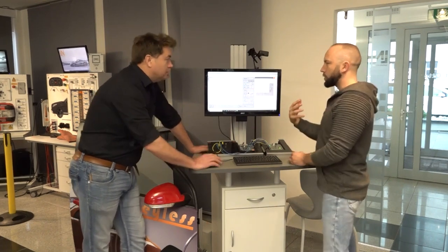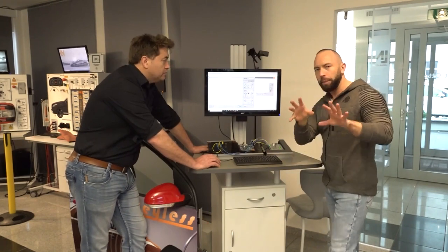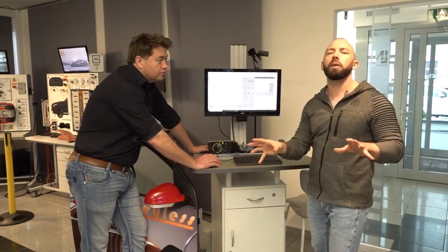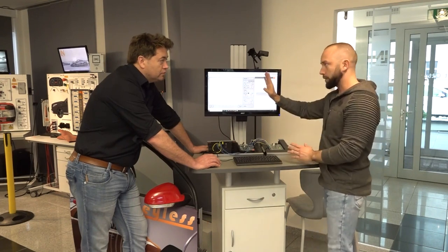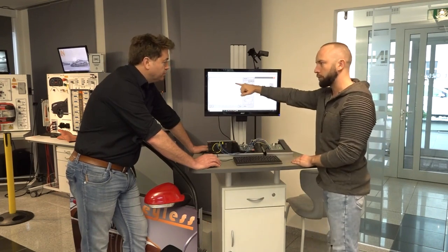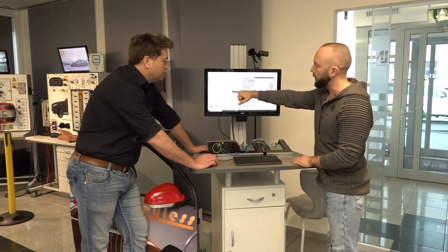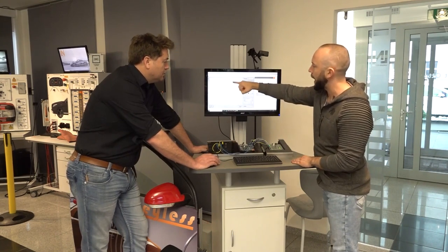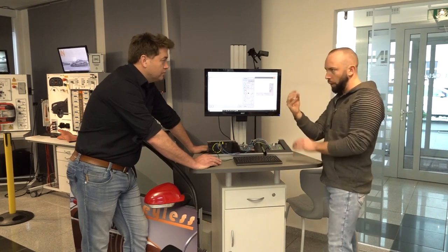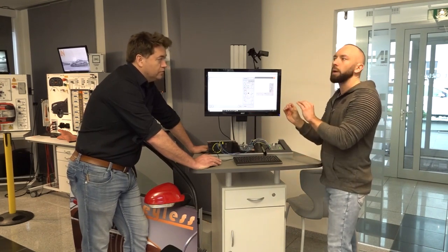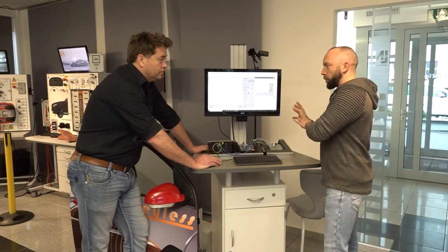Exactly. But sometimes it is said you can't use a multimeter for CAN bus, as you have to see the signal. But when we have, for example, a short circuit against ground from CAN high, or a short circuit against plus, this is also diagnostic information where you can see, okay, here's something wrong. I don't have to go further with the oscilloscope.